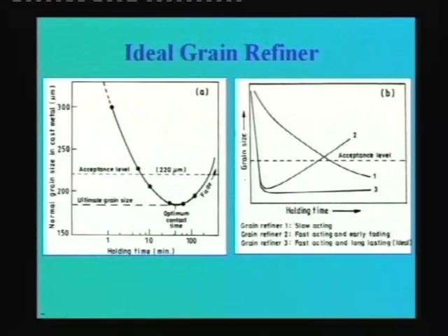For example, TiAl3 is about 3.5, TiB2 is about 4.2 or so. If you look at these high densities when compared to the liquid metal density of aluminum, which is about 2.4. Aluminum is 2.7, but when you liquefy aluminum, the density is much lower. In fact, it's about 2.35 or 2.4. So with that density, if you compare these particle densities, the particles are denser. So if you hold it for a long time, they settle down.